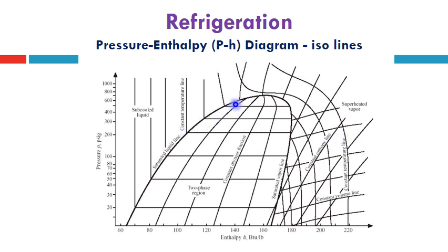The saturation liquid line commonly contains the outlet state of the condenser, or a state with a certain degree of subcooling, whether inside the condenser or outside, or even inside the liquid suction heat exchanger or outside it.